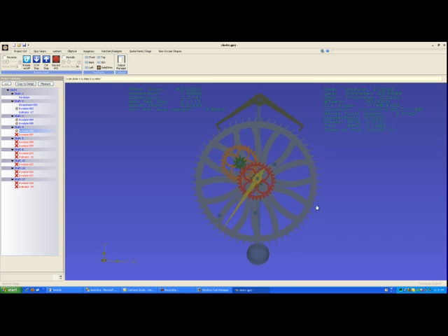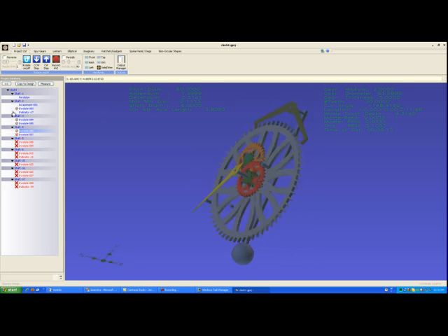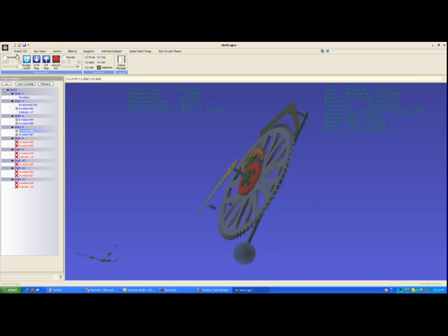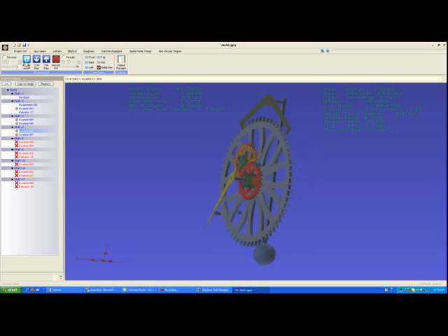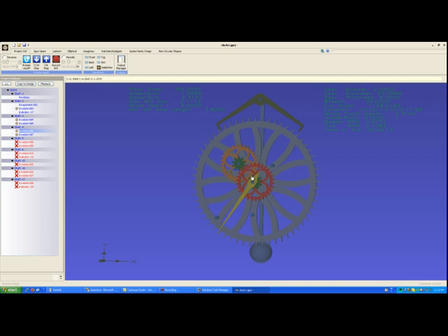I like a clock to look symmetrical. It makes it look pretty to the human eye. So I'm going to go in an opposite direction at 45 degrees or so. But to do that, I have to first add another pinion. So as you can see, I've added a pinion to this gear. Now, again, both this pinion and its gear are going to run free on the shaft. They're not attached to the deadbeat. So they would be bonded together. And in actual fact, I've used plexiglass glue to glue mine together, and they sit loose on the shaft. Again, that same pinion that I just placed will have a 9-minute rotation because it's bolted to the previous gear.